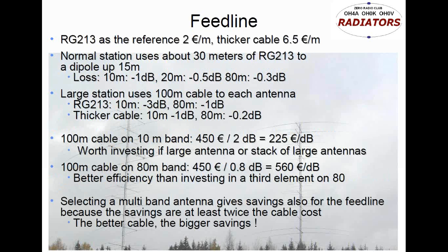Then if we are looking at the feed line, I have been using RG213, but then I started thinking, okay, is it worth investing into a thicker cable? If I have a 100-meter runoff cable on the 10-meter band, it was easy to understand that it's worth investing into a much better cable, even if you have to buy the cable new. I have been able to find surplus cables that are roughly the same cost as new RG213. So I have been very happy with my thicker cables.